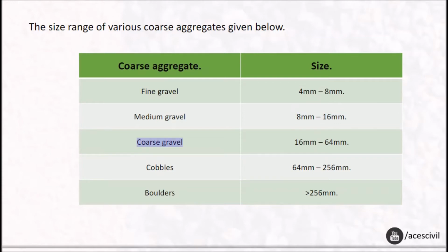Coarse gravel: 16 mm to 64 mm. Cobbles: 64 mm to 256 mm. Boulders: above 256 mm.